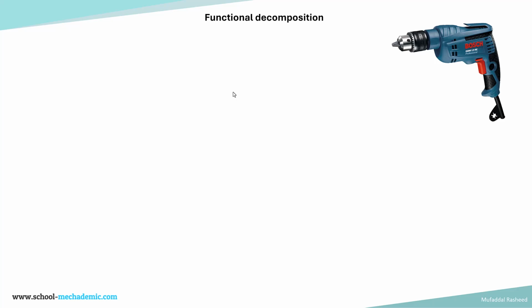Hello guys, in this video I'll be taking you through a very interesting concept in the mechanical design process, which is functional decomposition. Functional decomposition is basically decomposing the top level function into its various sub functions and understanding the relationships between them in terms of the flow of energy, flow of material, or the flow of information or signals.